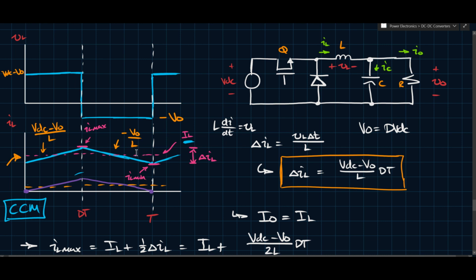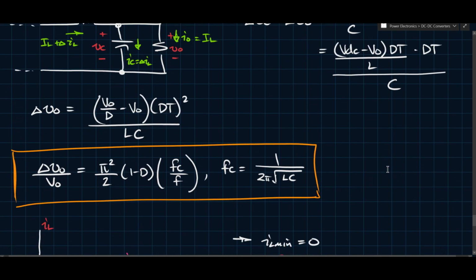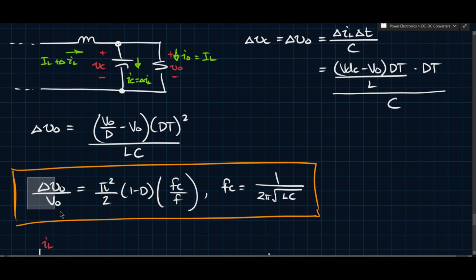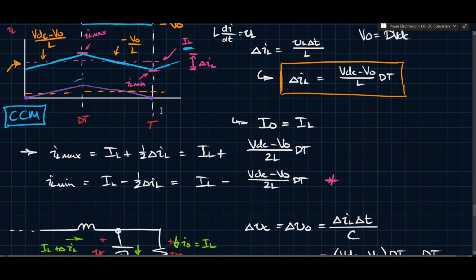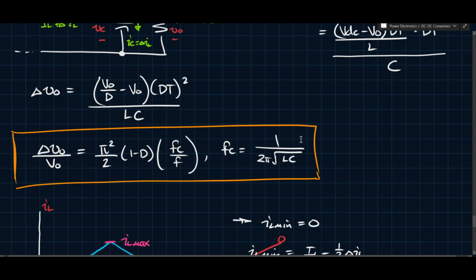we've basically sized its components and we've determined its mode of operation, right? And what do I mean by sized its components? I mean, if you want your inductor to have a plus minus, let's say, 2 amps ripple, you can calculate the value of L that will give you that. If you want your output voltage to have a 5% ripple, you can calculate now your C based on the value of L that you calculate from this initial thing here. You can then determine what value you need here, right? So this is a sort of design type of equations that you need.